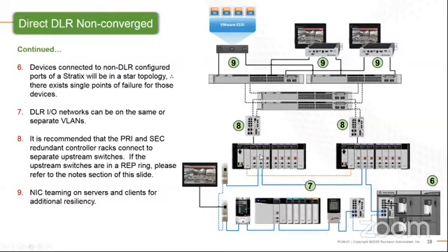Traditionally speaking, what would happen is they would have the exact same IP address range. When they first synchronize, your primary will have the first octet. Your secondary will automatically take your octet +1. So if this was a .5, this would be a .6. As it would do the swap over and you lose your primary, the secondary then would turn into your primary and would go from that .6 back down to .5 so that it would match up and all of the IO has the same ability.